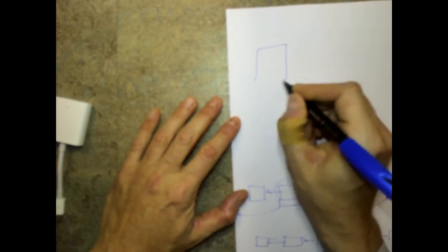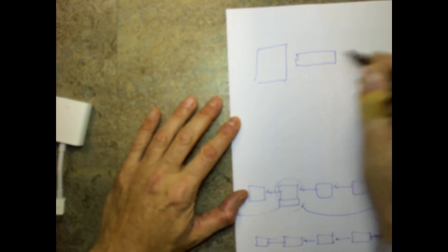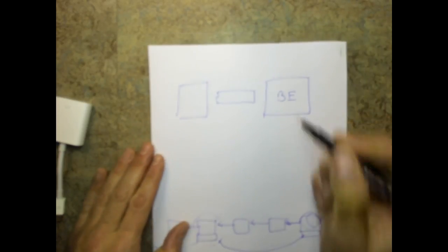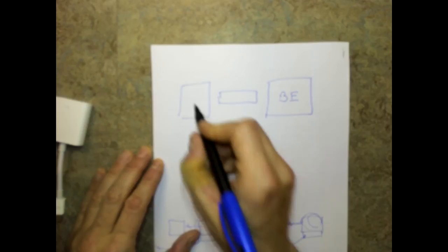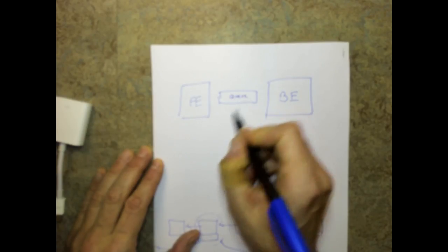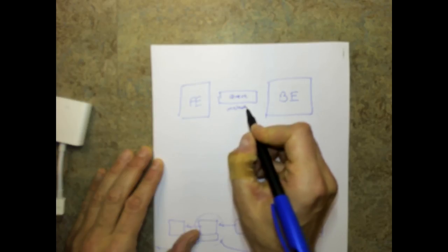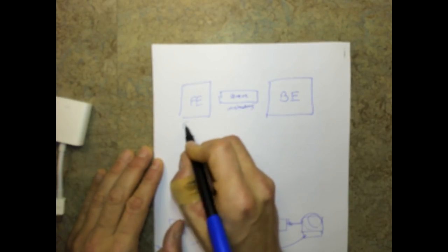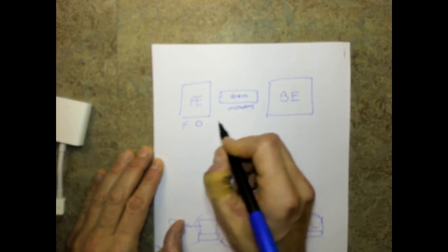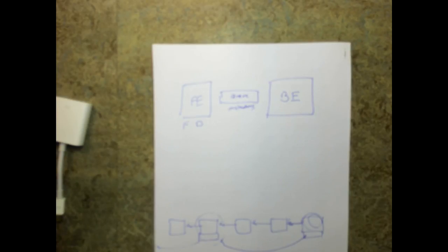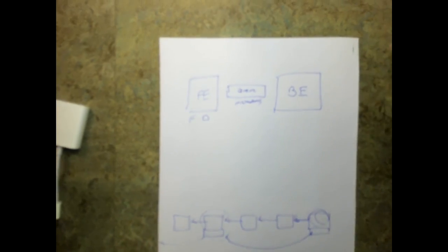Okay. So basically, the decoupled front end looks like this, at the simplest way of looking at it. You cannot see it. This is a back end. This is the front end. This is a queue, and this basically supplies the instructions. The front end consists of the fetch engine and the decode engine, and maybe the rename engine, maybe the register file access also. We don't know, depending on the engine over here.